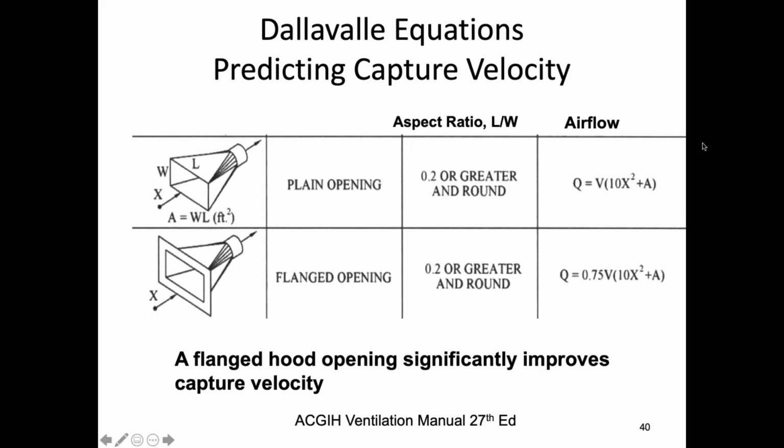Yeah, flange duct. Why the flange duct? The flange duct, because when we have an unflanged duct, it's going to pull air from all directions, from the front and around the sides. So the flange discourages it from pulling air from behind the ductwork. So the same amount of static pressure here will give you more velocity at the same distance in front of the ductwork. So we're going to see if I can find some cardboard, and we'll set up a little flange duct here to see if we can measure that.